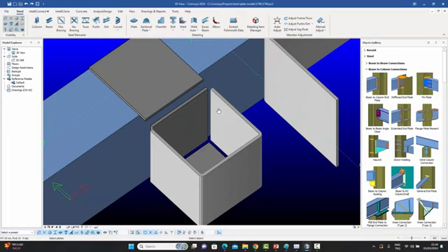I can then continue to join this whole new bent plate and this last piece over there, this one, and this one. And now, because it sees more than one possibility to connect, one common edge is over here and one over here, it asks me to choose which one I want. So I choose this one. And when I do that, that one is connected.